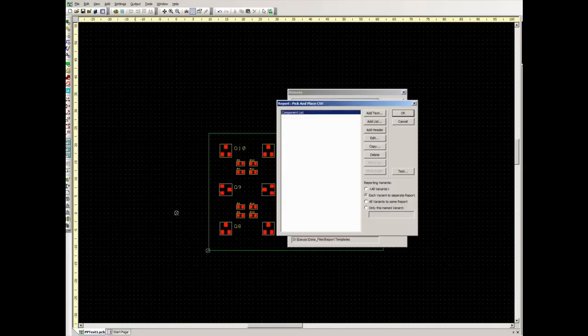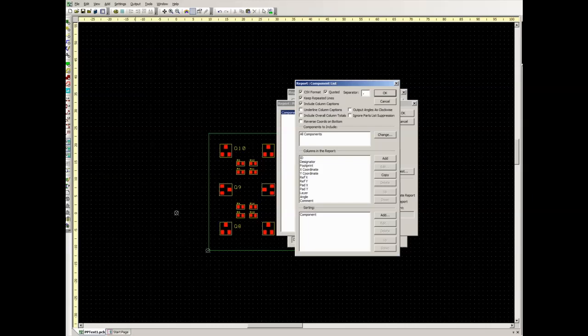I'll give you a quick look at what's in there. Now, although you could export just the coordinates and the orientation and the name of the components and then create the extra columns in Excel, I've found it easier just to create some dummy fields that I will manually edit within the CSV file externally. That just makes sure I don't forget any and also keeps them in the right order.